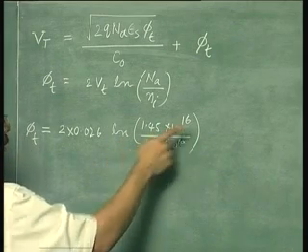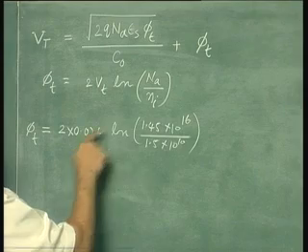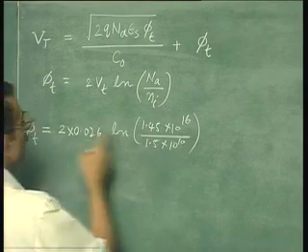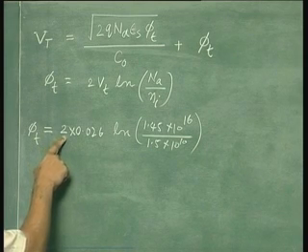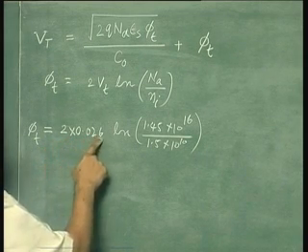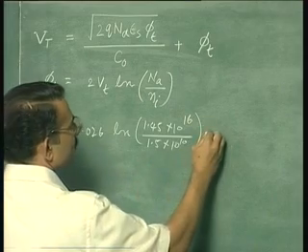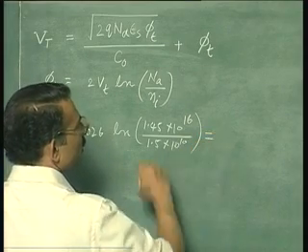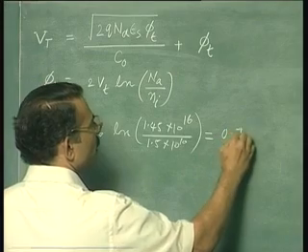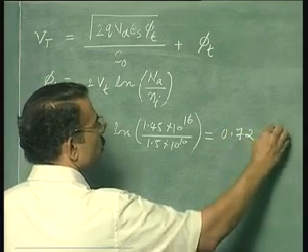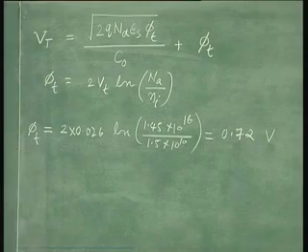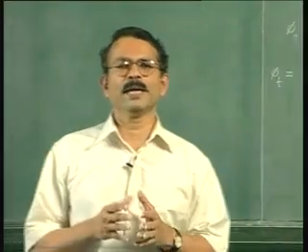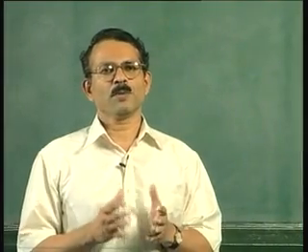So when you take log of 10 power 6, 6 will come out and you will have ln 10. So that 6 gets multiplied by 2, you have 12. So 12 times 0.026 into ln 10. It turns out that this quantity will be about 0.72 volts. So this phi t value is somewhat like the value of the built-in voltage of a p-n junction, okay, about 0.7.